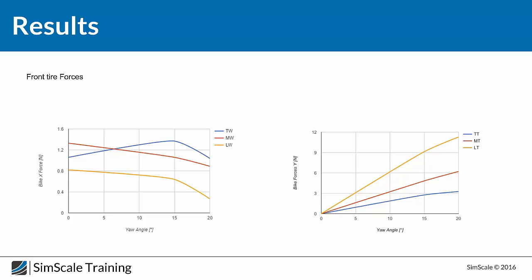And this really shows that. The large wheel has a larger surface. You would expect it to have more drag, but since the flow is not separating so much and is going around the wheel much more smoothly, in the end we have less drag.